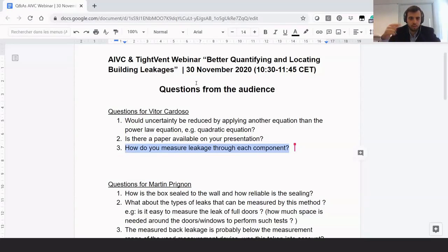After, we seal the heating and air conditioning and measure again, until all the leak types were sealed. Then we measured, and about 7% of the total air leakage of the envelope could not be associated to any of the types that were in the initial plan.